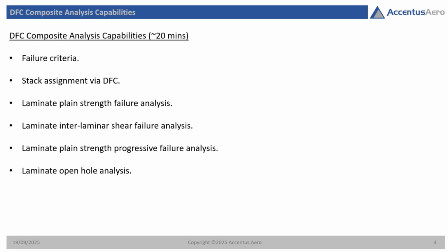Right, so the topics we're going to cover today are the explanation of the failure criteria, how you can assign stacks via DFC to Apex, how we perform a laminate plane strength failure analysis, the laminate shear failure analysis, then a progressive failure analysis, and our open hole analysis.